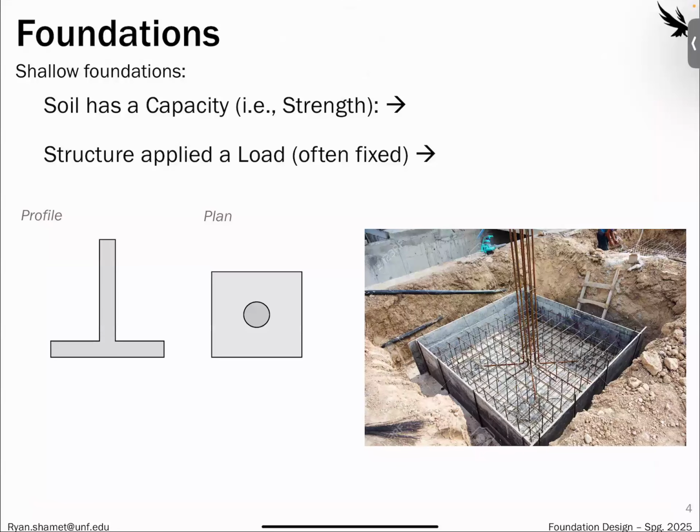So let's recap a little bit. We were talking about the shallow foundations, and what were the two things we learned to design for shallow foundations? Bearing capacity. Yeah. Bearing capacity is the shear failure due to a foundation. So we know that soil has some type of capacity or strength. And we show that as a q ultimate, or q.